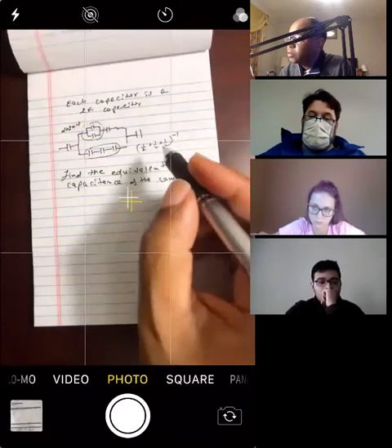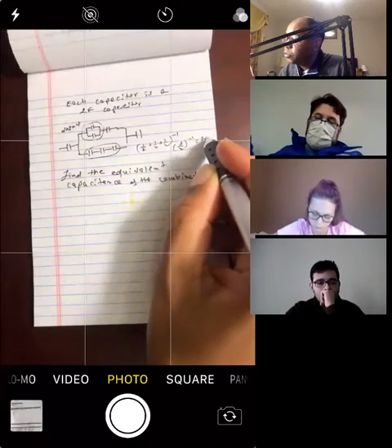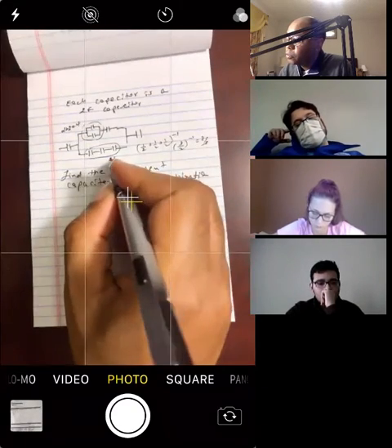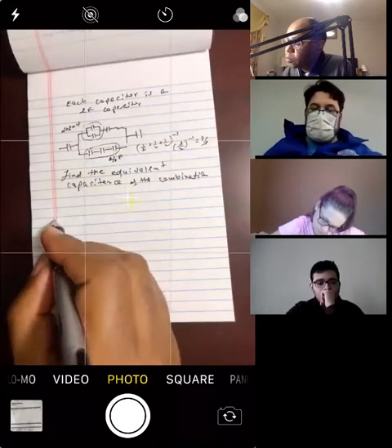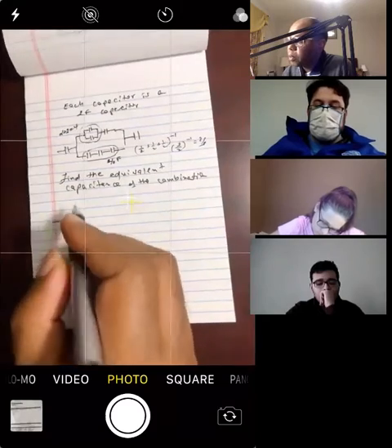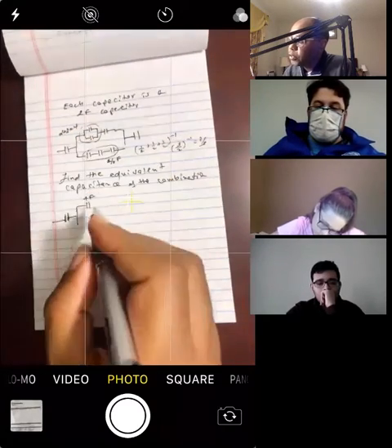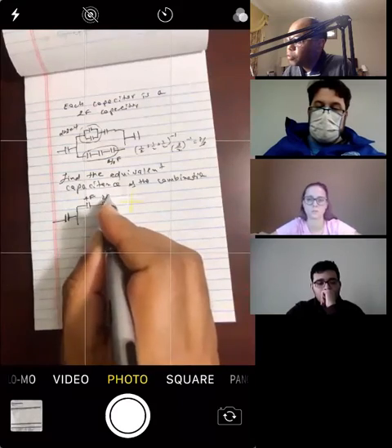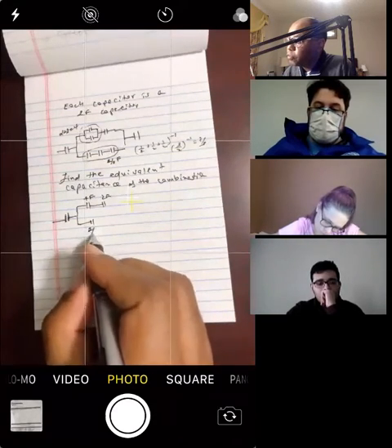That's how you do it. So that's 3 over 2, inverse, that's going to be 2 over 3. So these are equivalent to 2 over 3 farad, okay? So I've got a new simplification over here. I've got a new combination over here. I'm going to replace this by 4 farad. Okay, this over here. I still have this 2 farad capacitor over here. I replaced all these three by a single one, which is 2/3 farad.